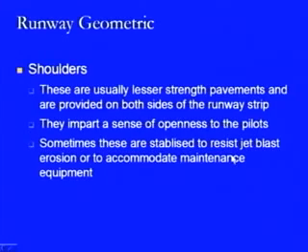Sometimes these are stabilized to resist jet blast erosion or to accommodate maintenance equipment. That is on the basis of the requirements. If the maintenance equipment has to move, then they have to be stabilized, or at times they have to be made a little in the form of a pavement, not maybe having the full strength as being provided in the case of a runway strip.